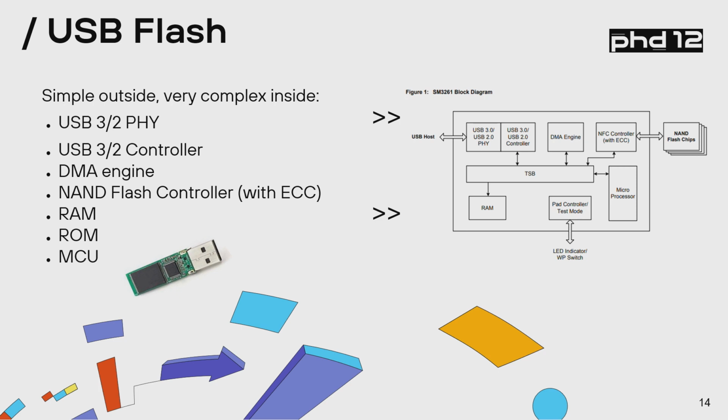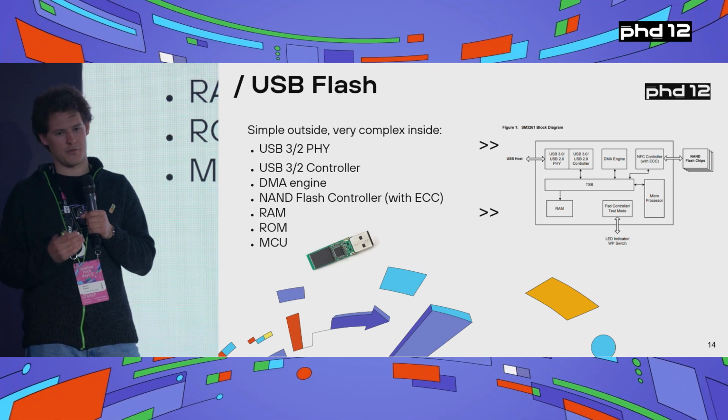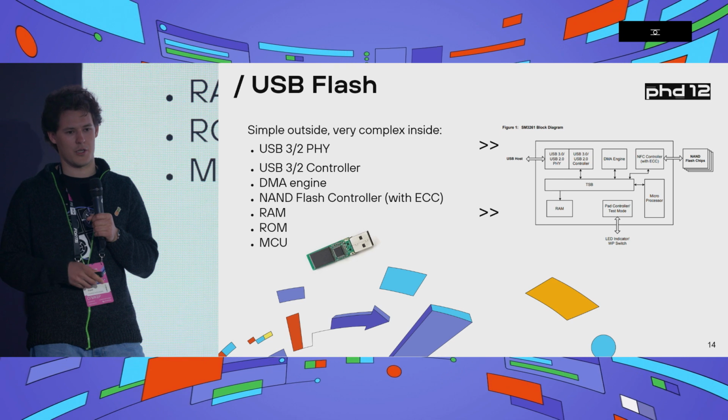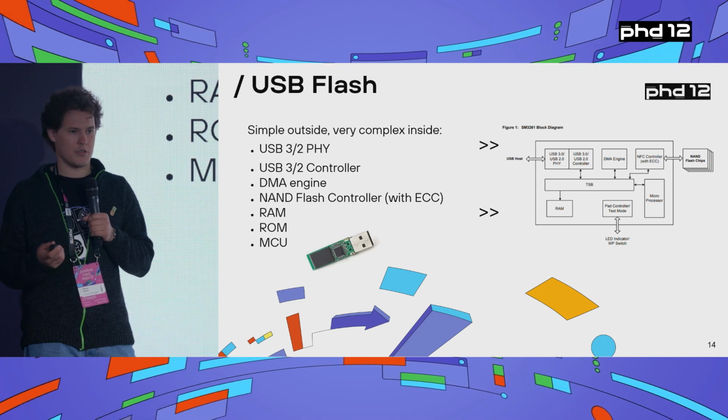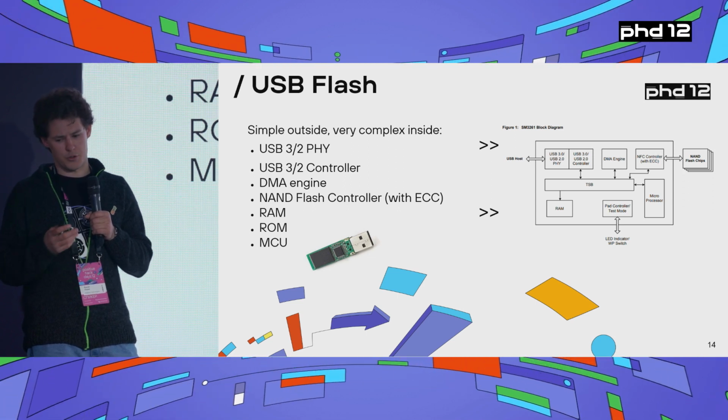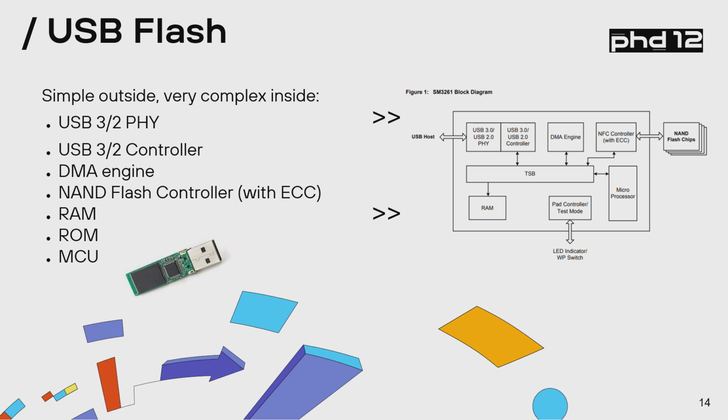So obviously, you'll need to wrap your mind around the USB controller. Say, if it's a USB 2.0 drive, which is quite complex already, but a USB 3.0 controller will be colossally challenging. So you will need to rely on your intuition that, okay, maybe data has already arrived, and then you see in the firmware that some data is being processed. And then in a different hardware register, you will see another bit emerging. And then you convert data from USB controller to NAND controller.